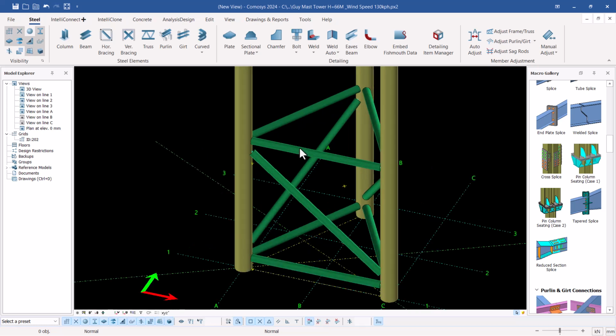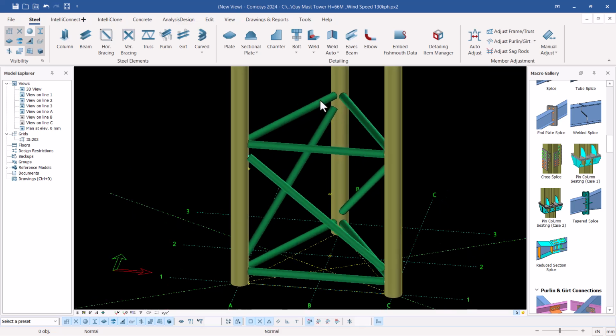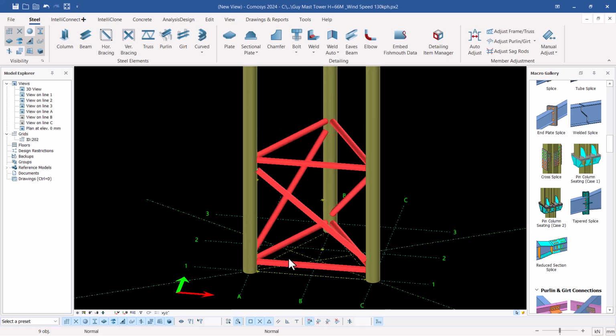Once we've done so, we need to populate this upward. How do you do that? I'll select that and rotate it and put it in a position that I'll be able to copy it, then select everything like that, press Control and select that, select that, select that, and select that. Once I've selected that, we want to populate this upward. Since we have this horizontal brace on top here, if we copy this, there will be a copy on top of this, so that will not be wise. So I'm going to press Control and eliminate this.